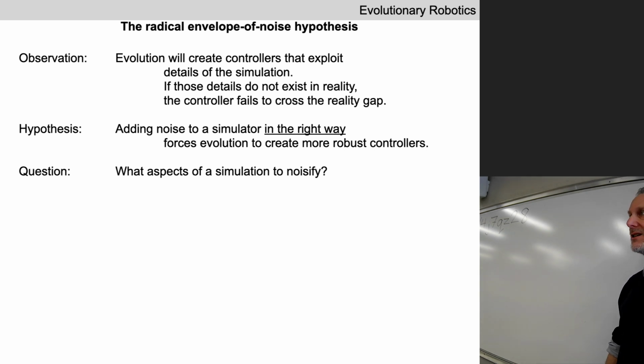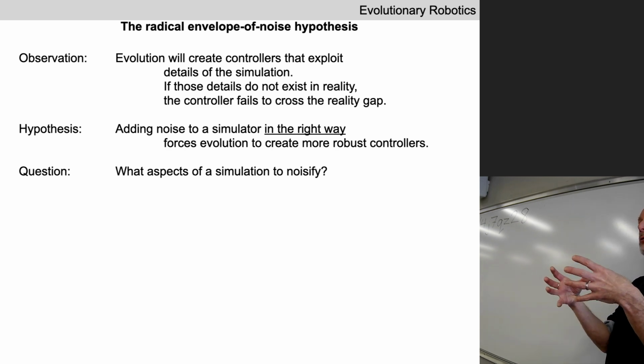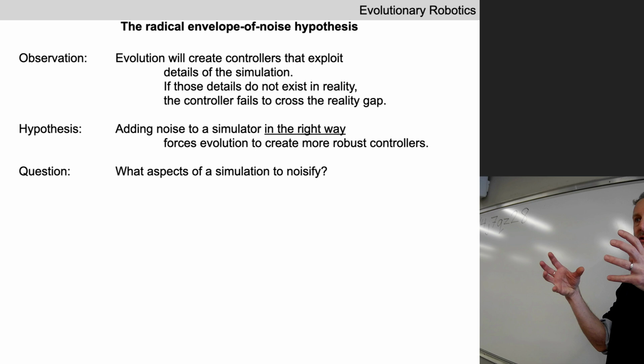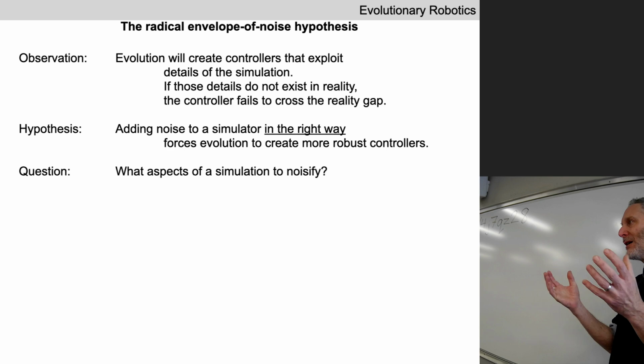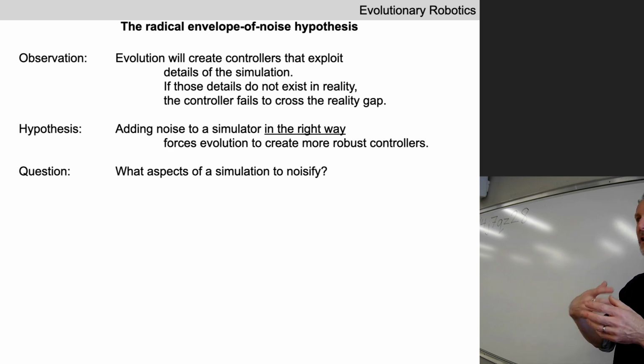That is relatively constant here. What are some other aspects of simulation that are not so constant? Maybe the strength of the motors. Strength of the motors, right? We were just talking about details of the mechanical construction of a robot. You're going to build your quadruped in reality, and that quadruped has 8 motorized joints, so you need to buy 8 motors from Amazon. You order 8 motors, you build them into your robot. Those motors are going to be slightly different. You pay for expensive motors, they're all going to be relatively the same. But as you start to use your robot for hours and possibly days, those motors are going to start to experience a little bit of wear and tear. And they're going to wear and tear in slightly different ways and become different over time.